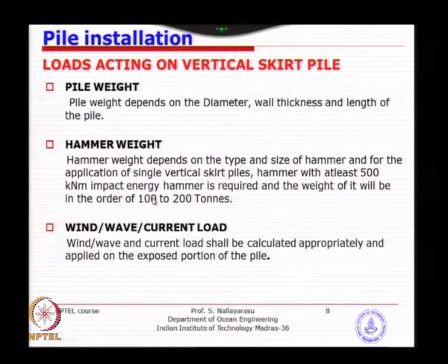You will have the hammer, you could see if you go back to this picture, this diameter is almost 3 meter. So, you can see that the size itself is very large. The length will be about 20 meter, the hammer size, from here all the way down to the casing level down here is almost 20 meter. So, you could see that the weight could be considerably larger, and once you place the hammer, it all depends on whether it is a vertical pile or an inclined pile.